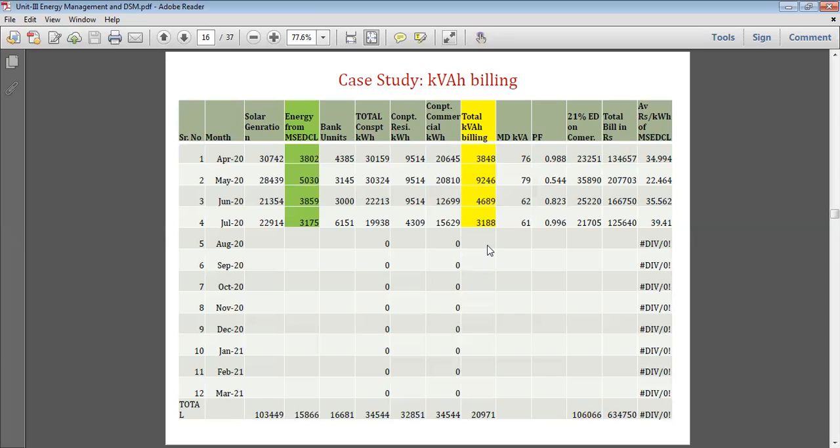So power factor maintenance is the first lesson to do energy management. It has numerous advantages, technical as well as economical. Technical advantage is that if you are maintaining the power factor, the current drawn by the transformer and the load will be smaller. Definitely, when the current is smaller, the switchgear, whatever the MCCB, MCB, and circuit breakers required, will be of a smaller capacity. And hence, if the current is smaller, there is no problem of overheating and maintenance also.